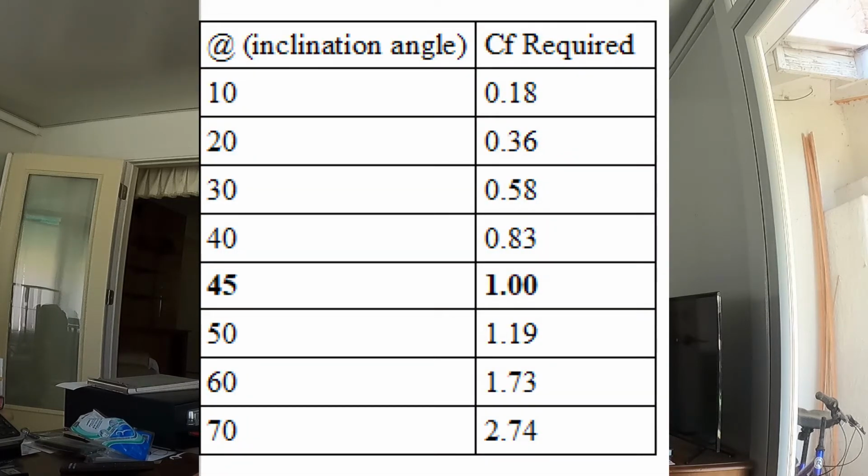Of note is that at an angle of 45, the coefficient of friction is 1. So the coefficient of friction cannot exceed 1. So all the table values which exceed 1.0 require gear loading on the tire treads to continue the climb. In practice, any inclines greater than 30 degrees probably require some degree of supplemental tire gear loading.